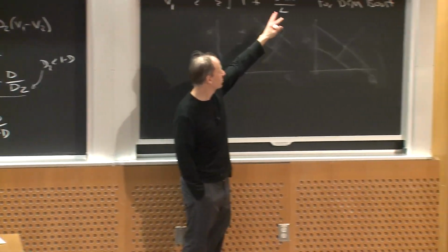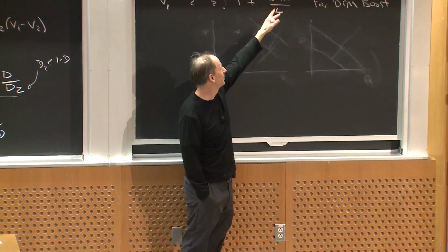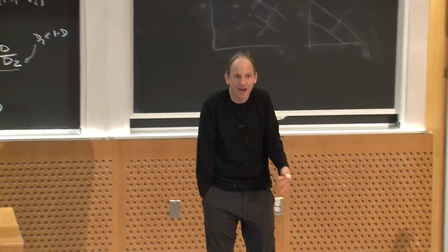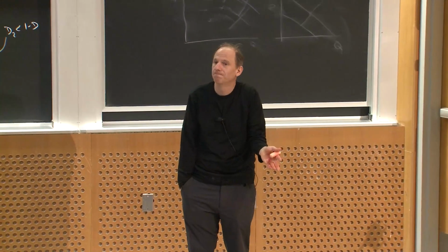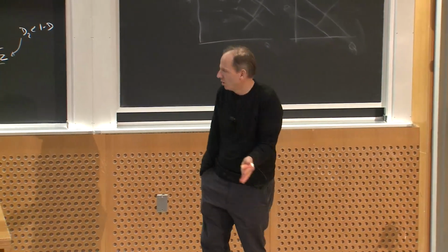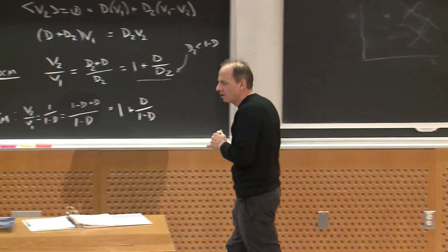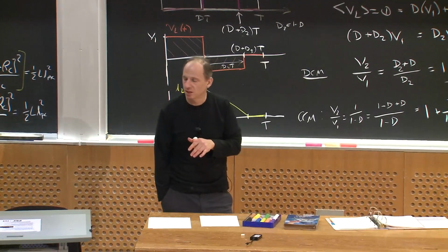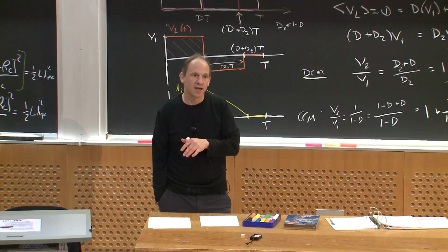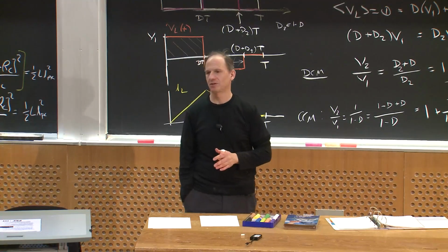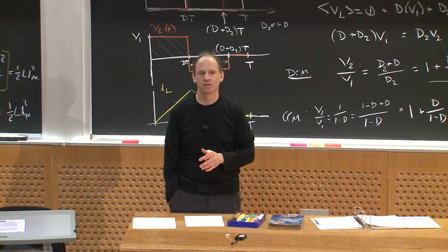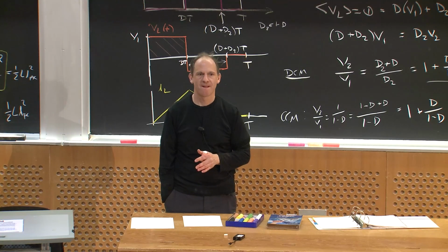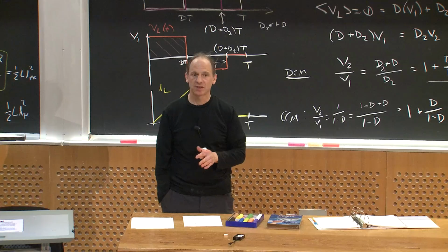It depends on my load resistor. It depends on my switching period. It depends on my inductance. It's a mess. It doesn't mean you can't do it. It's just not a simple relationship anymore. So suddenly, it's a lot more complicated than it was in continuous conduction mode. And it also affects the converter's dynamics, as we'll see. Any questions about that? But that said, we can't avoid it.